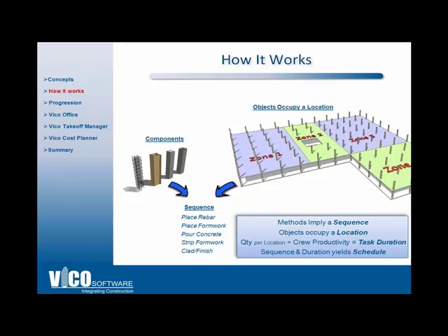Finally, you'll be able to group these components according to different zones. You can break down the model based on construction zones, based on your construction sequence, or based on estimating zones. If you have a lobby area, you'll be able to break down the quantities for that lobby area alone and create an estimate that will include the quantities from that area and will isolate the quantities for that area automatically.